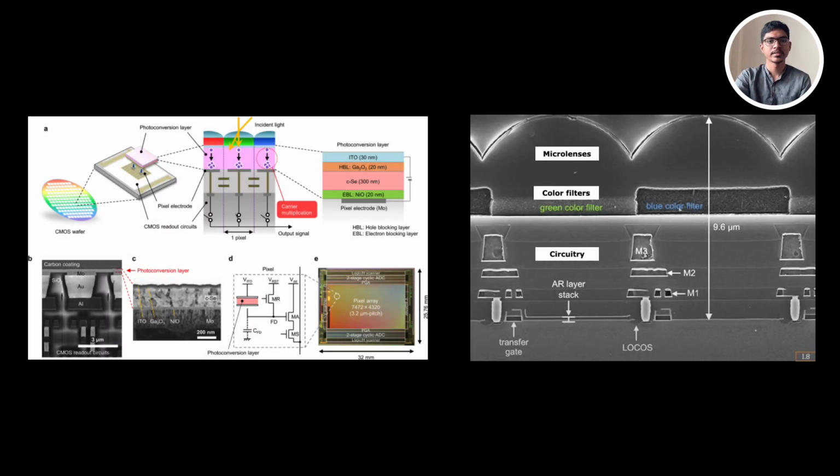There is more to an image sensor. Here we can see the potential wells corresponding to the pixel. But then on the top of each pixel we can see a color filter. A pixel doesn't really know which color of light is arriving there. It is just counting the number of photons. So in order to measure color, we are going to use the color filter sitting just above the pixel. And at any given location, we can only measure one color.